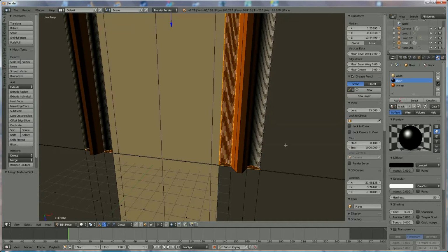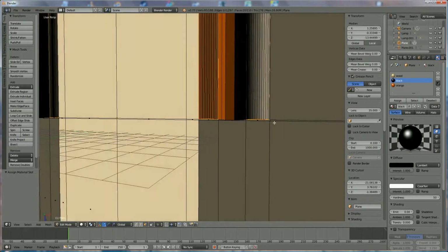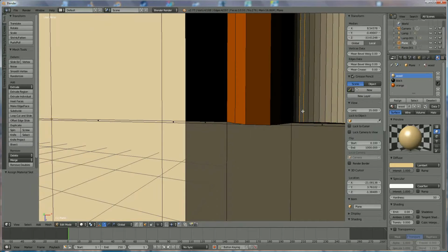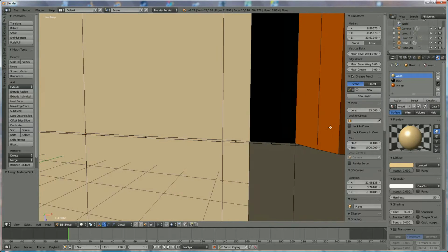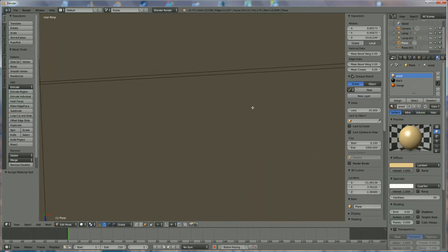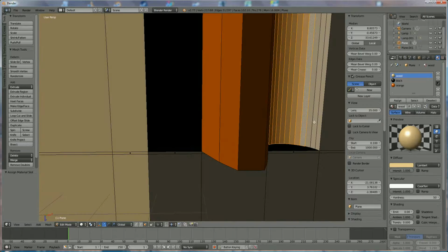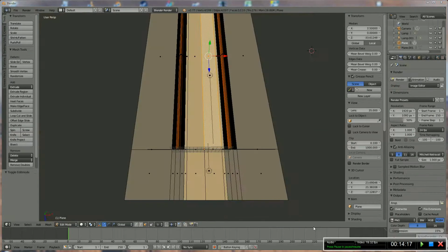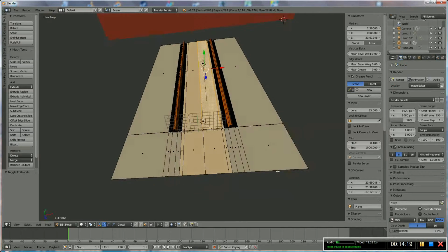There's black and assign, and these selections that I have selected are already black, so we're going to select the other. For instance, right click on that one, right click on that one, and you can go on like that. I think that's better that we come back when I've done everything in black. So again, selected everything, press black and say assign. I'm going to do the same over here, and then I come back. Now we're back, so this is done.